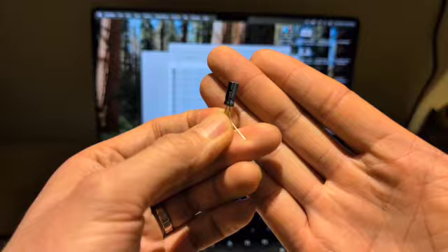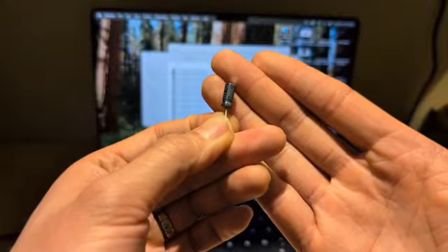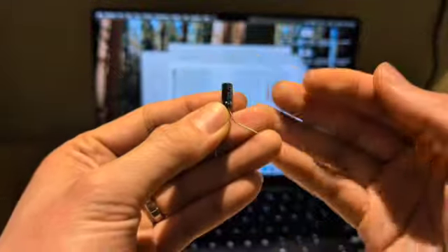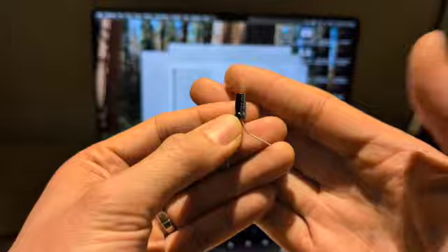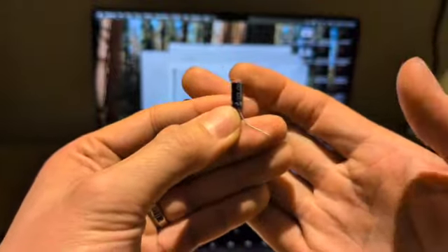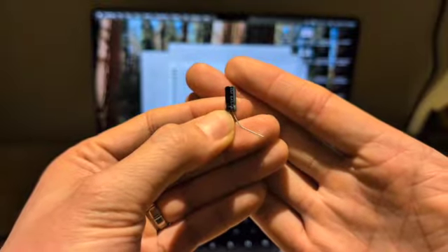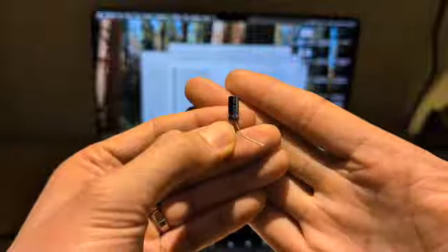And what it's telling me when we're charging this in the experiment is that, well, if the input voltage is still 5 volts and the capacitor is only reaching about 4.6 volts, that means the resistor is dropping the remainder of the voltage. And what does that mean? Well, it means there's a current flowing through. And the reason why there's a current is because there's a loss in the capacitor.